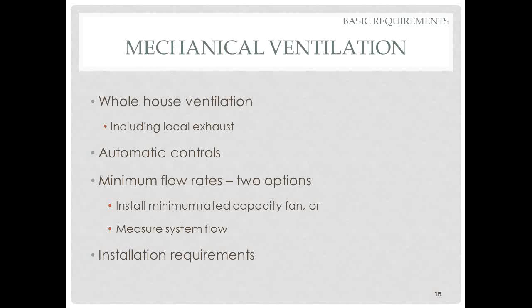Or you can put in whatever system you want and have it actually measured to see how much air it's moving. There are also some miscellaneous installation requirements for ventilation systems. Most of these have to do with constructing the ductwork so that the airflow is not restricted. Also, a couple of the installation requirements have to do with noise, trying to get the system reasonably quiet so it doesn't annoy people, and they don't shut it off.